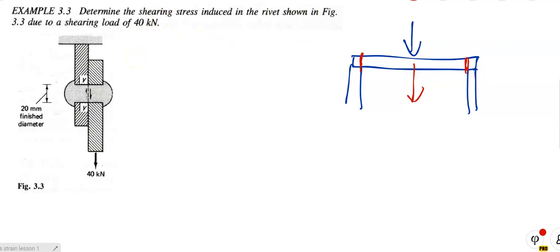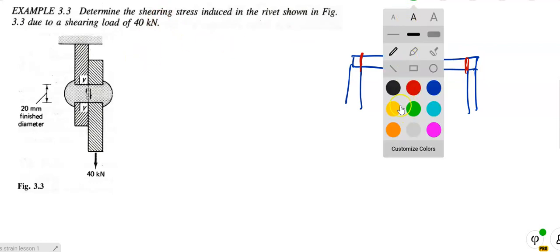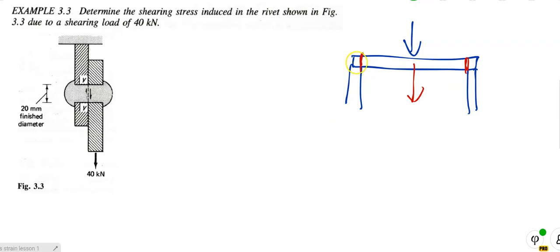But what we do in real life is we actually put steel bars in there like so, to resist those shearing stresses, so that the beam and the column and the structure stands up nicely for the rest of its working life. So the kind of stresses induced inside that kind of member, on those planes there, is called shearing stresses. So that's a little bit about shearing stresses.